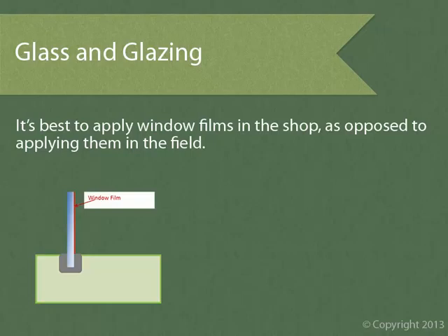But an even more important benefit with relation to exterior skin coordination is that we want the edges of the window film to tuck into the mullions. The window film depicted in this illustration was installed after the windows were complete, so its trimmed edges are exposed. Odds are the trimming won't be perfect and will have some exposed glass around the edges. Equally importantly is that the exposed film edges are going to be prone to peeling.